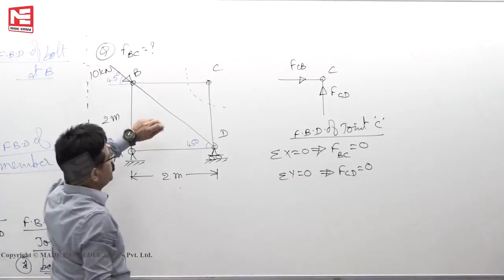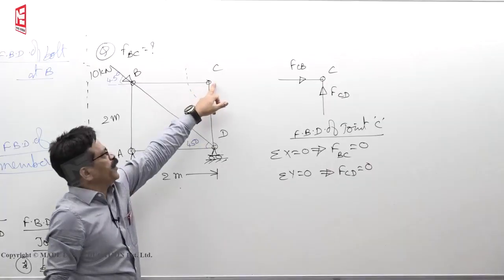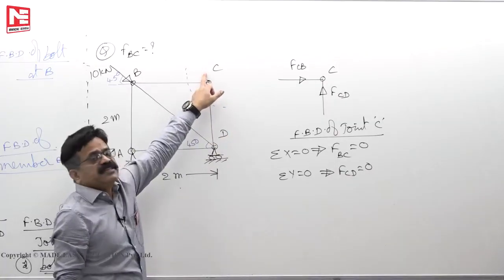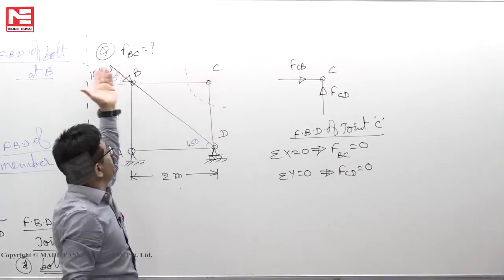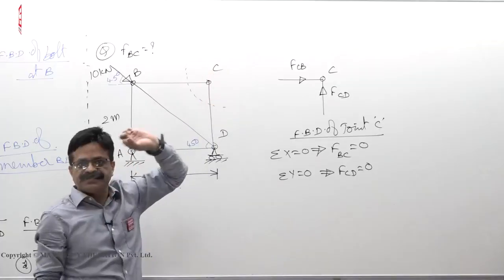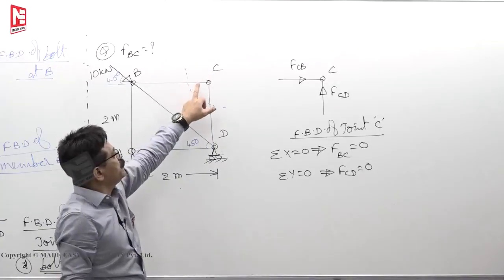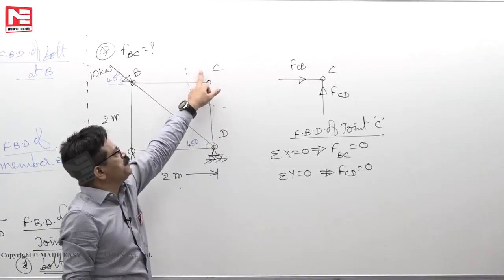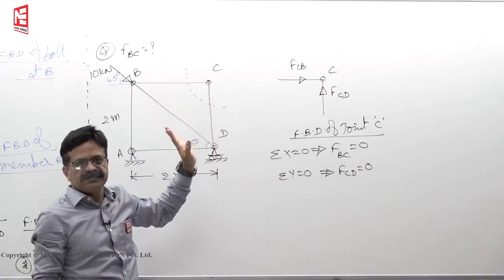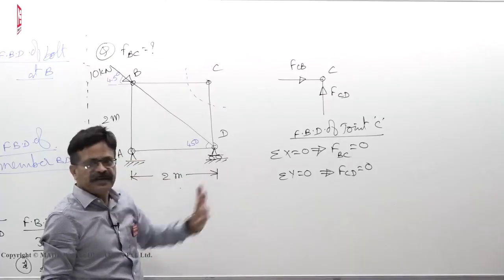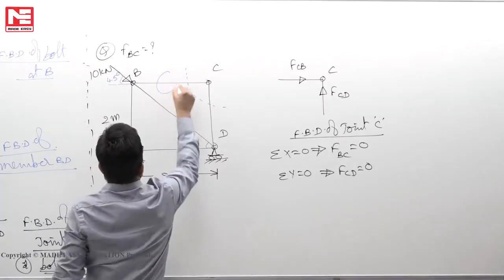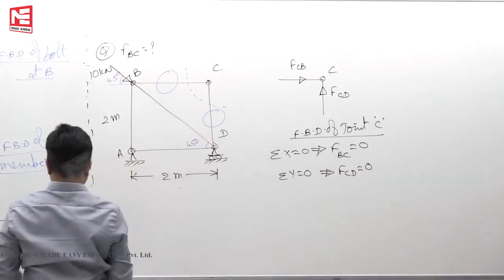Okay. Now, at this joint, 2 non-collinear members are meeting with no external load at this joint. Other end there may be 10 or 1000, it has no influence on this joint configuration. So, 2 non-collinear members, no external load. So, for the structure to be in equilibrium, both members have to be 0. Otherwise, it will not be in equilibrium like this. So, having found that this is 0, this is 0.